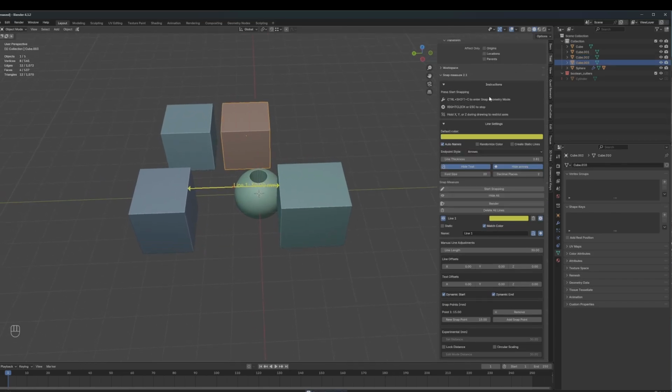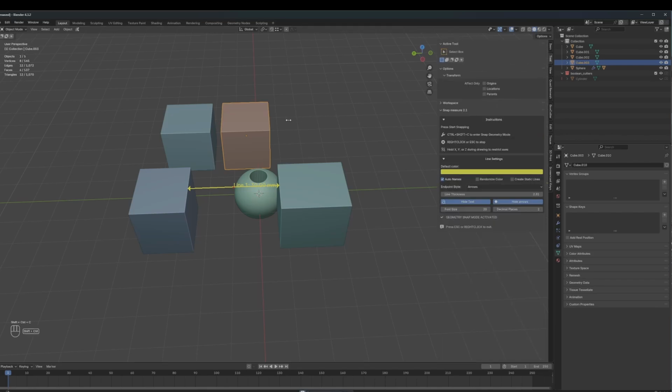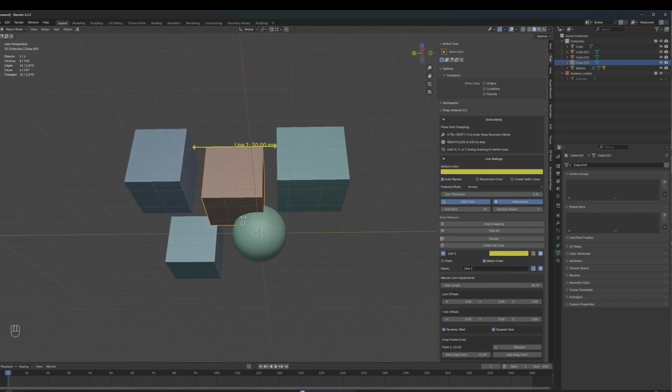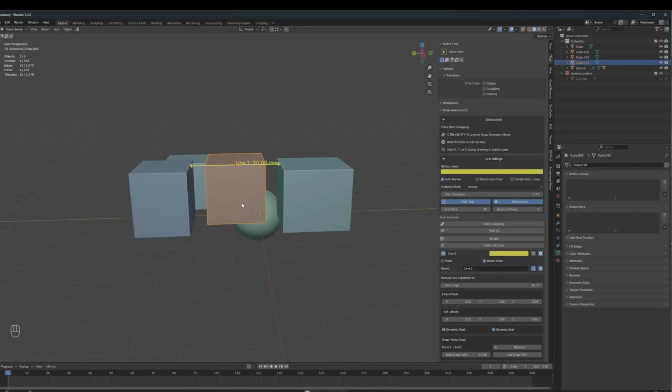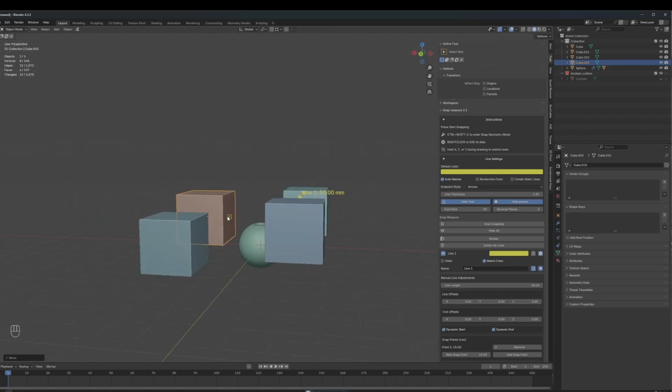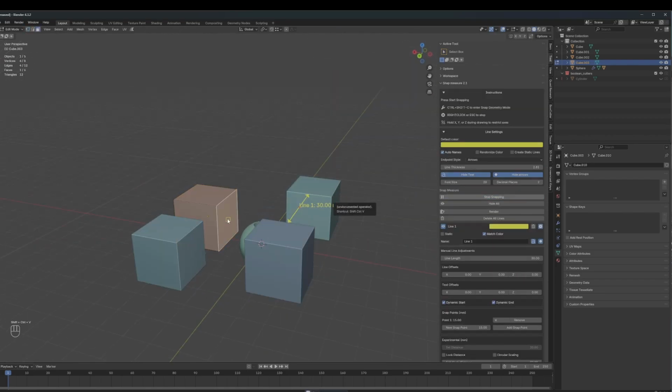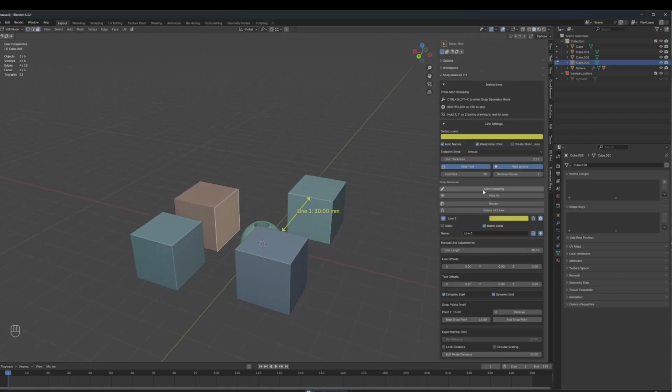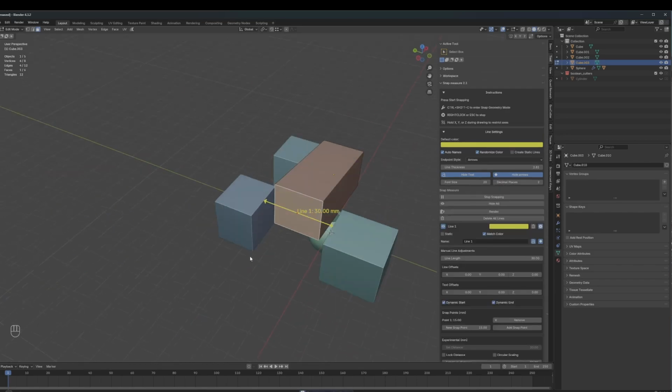If you press Ctrl, Shift, and C during the modal operation, you will enable geometry snapping mode. You can then select and hover the object you want to move. Click on the part of the object you wish to move and drag to either a virtual snap point or another object and release the mouse. This behavior works for object mode, which will move the object. If you toggle to edit mode, the selected mesh will then be moved to the desired location.